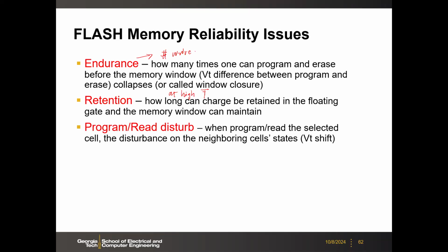And then if you look at other applications, because there are different grades of the products. If it's commercial grade for the electronics, 85 degrees. And then if you look at the other one, like the industrial application, I remember it's around 125. And then the even higher grade is automotive, under your engine hood. That one is probably like 150 degrees C. So your data retention needs to be satisfied at those temperatures, depending on your application.